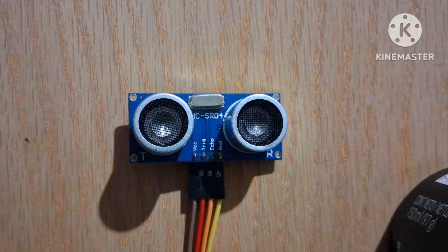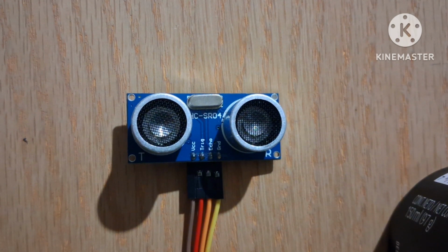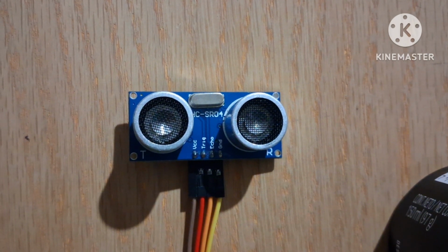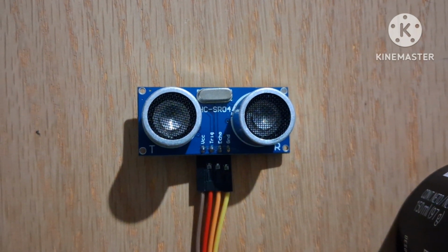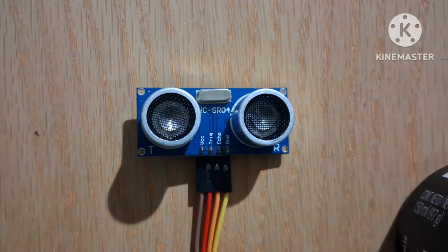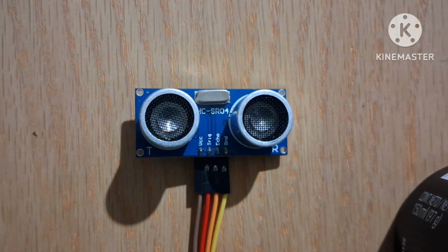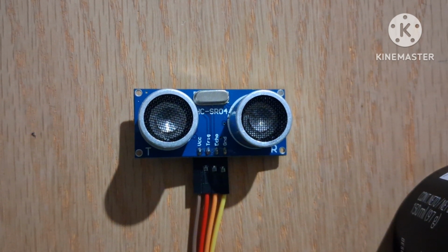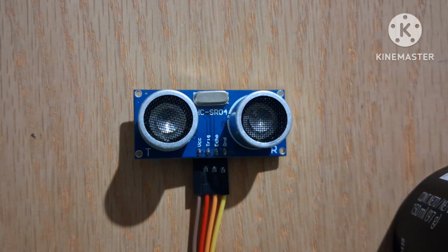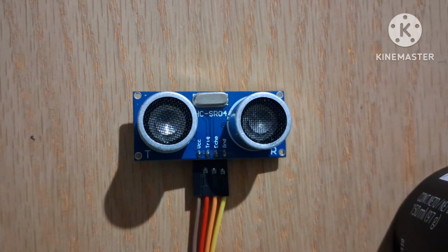Well, the ultrasonic sensor has 4 main pins. VCC, which is to be powered with 5 volts. The trig pin sends an ultrasonic pulse with a frequency of 40 kHz. At the moment of impact it is returning, and this is where the echo pin comes in, which is responsible for measuring how long it takes to return, and as explained in the code, to obtain an approximate distance.